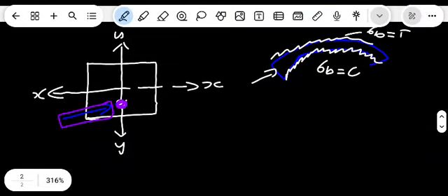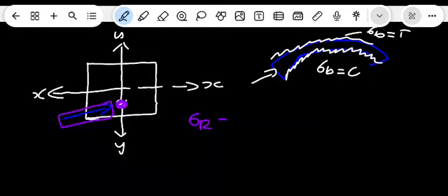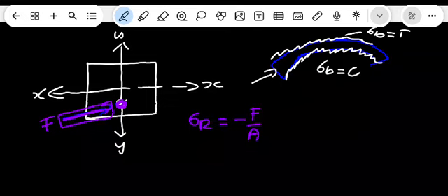So what about now? We want the resultant. I want you to understand this is the force that will apply. This is pointing towards the section. If it's pointing towards the section, we've said that it's compressive, whereby compressive is negative. So you will have here negative force divided by the area.